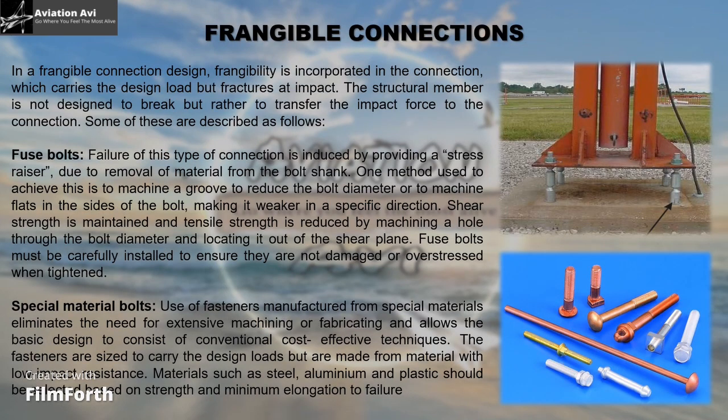Another way of making equipment frangible is by making its connection frangible. So, in a frangible connection design, frangibility is incorporated in the connection, which carries the design load but fractures at impact. The structural member is not designed to break, but rather to transfer the impact force to the connection. Some of these are described below.